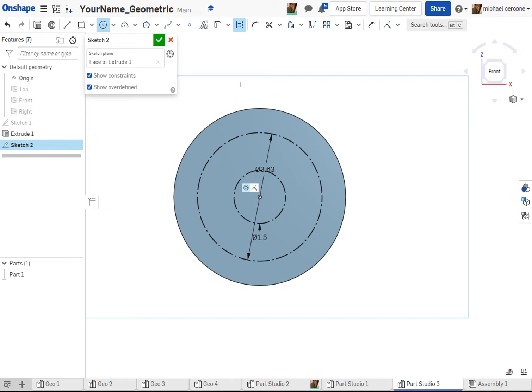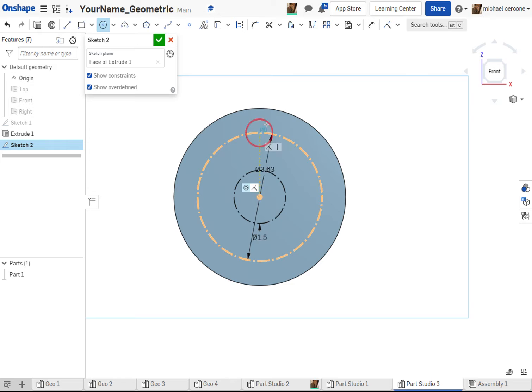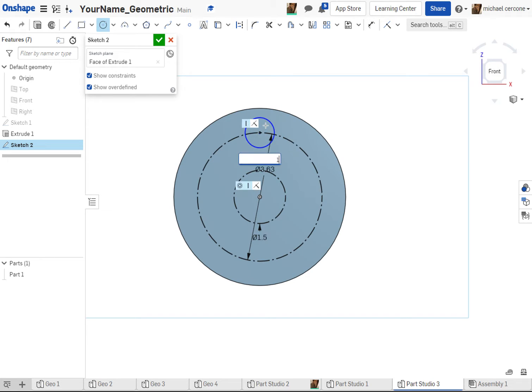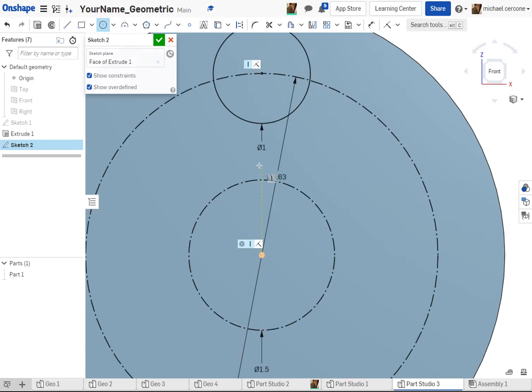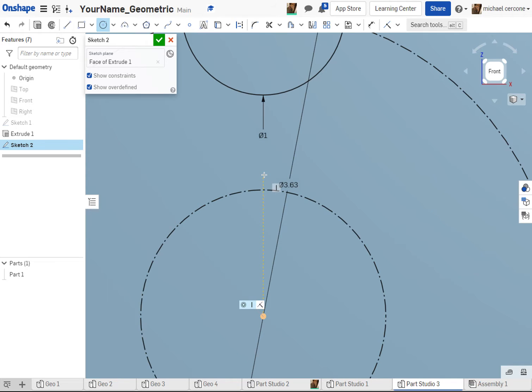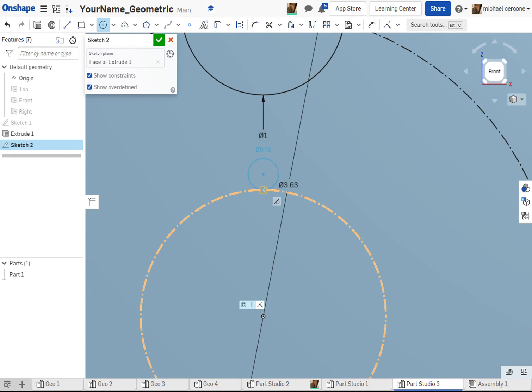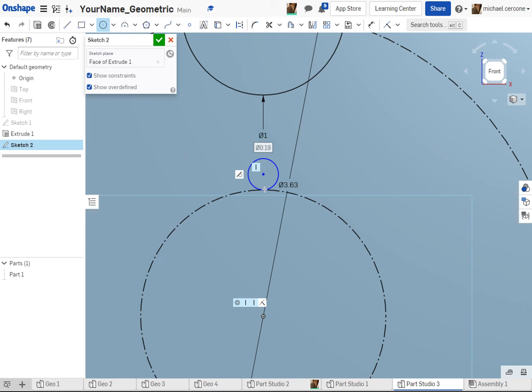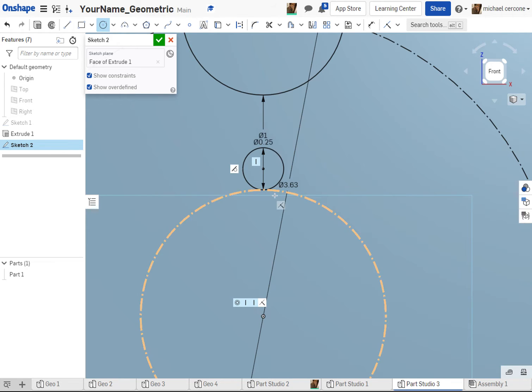Now I have 2 circles. I have a 1/2 inch radius at the top and then an 1/8 inch radius at the bottom. Neither are for construction. So this top quadrant here, this is a 1/2 inch radius, so 1 inch diameter. And here, this one, it's not on this arc, it's coincident to it, so I'm making this go vertical above and moving my cursor straight down like a tangent. And this is an 1/8 inch radius, so a 1/4 inch diameter. So that will define that.